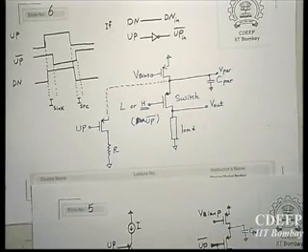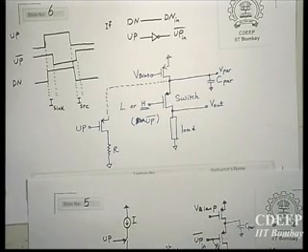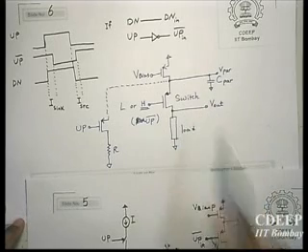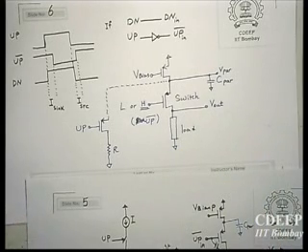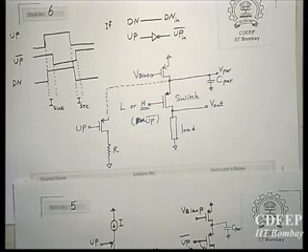And because the current source doesn't turn off, the voltage at this node doesn't reach VDD, and the problems are less. But it's not like it is completely omitted, because anyway the voltage here may change compared to the voltage you had previously. So similarly, you can provide the same path for down.